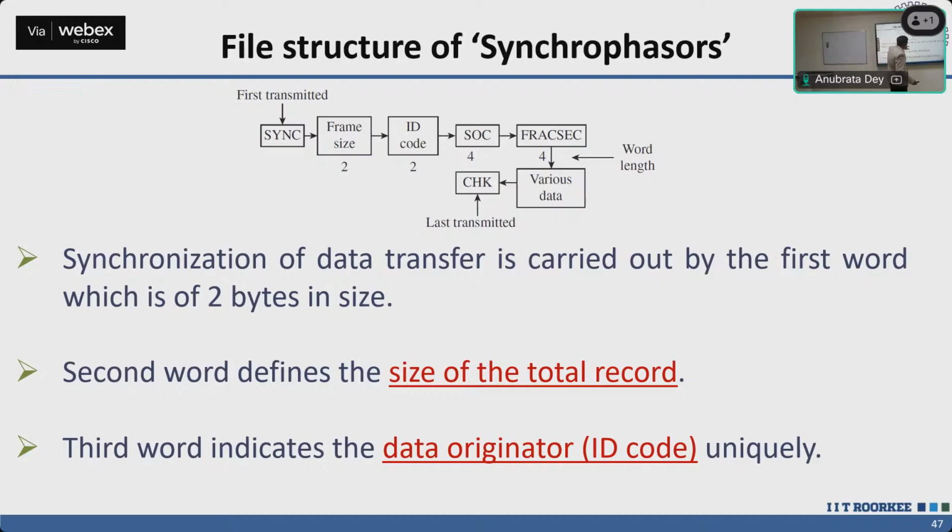Now, how is the PMU going to calculate the magnitude and angle of the three currents? They take some data. Obviously, one cycle of data is required: the instantaneous values of all three currents for one cycle, 20 milliseconds, I think n plus 2 samples, where n is the number of samples in a cycle. That much data is required for calculation of the phasor value.